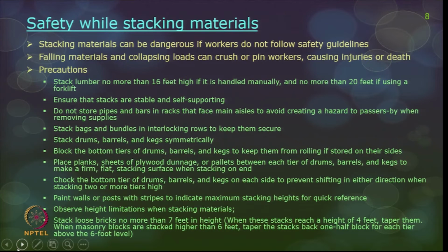Do not store pipes and bars in racks that face main aisles, to avoid creating a hazard to passers-by. And when you are stacking the material, you should always allow movement of the workers without disturbing the stacked loads. Stack bags and bundles in interlocking rows to keep them secure.